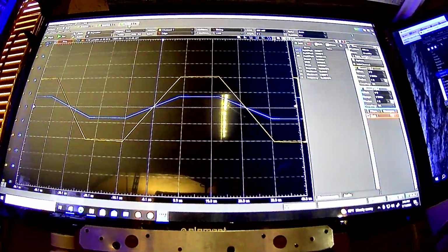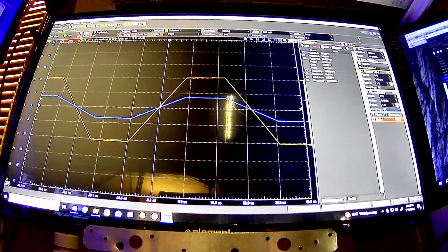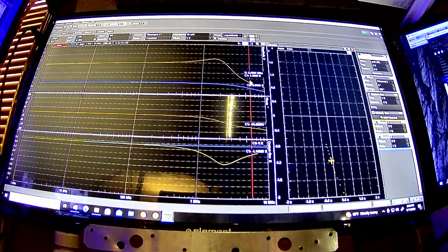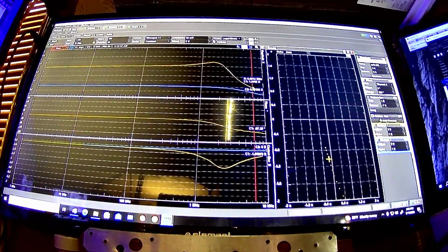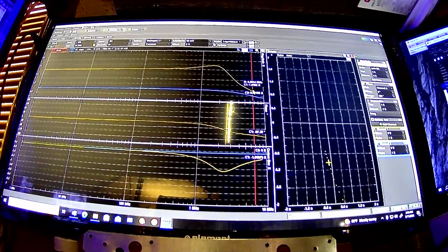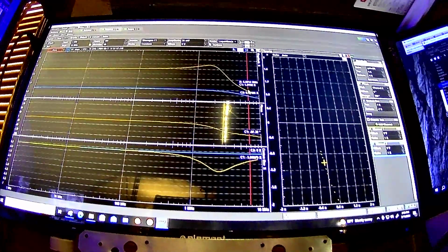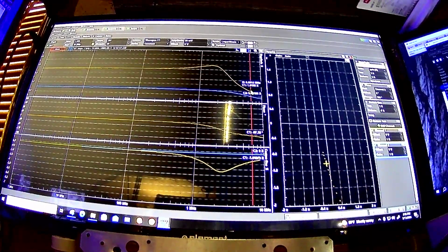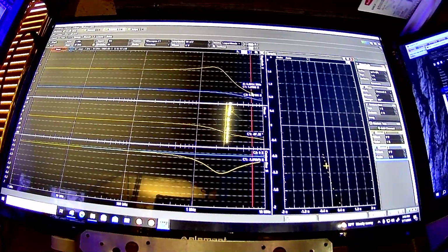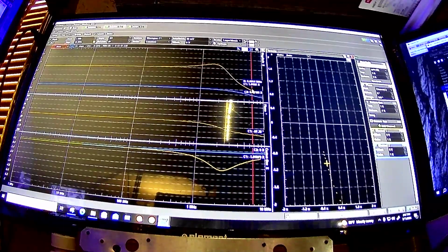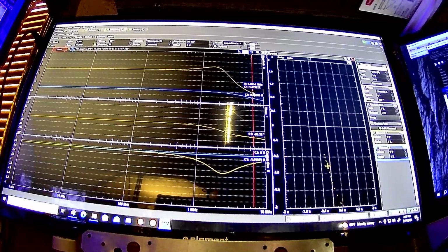Now, because this NE5532 is a 10 megahertz op amp, and it's showing unity gain down to about 6 megahertz here, which we got set to a gain of 3, that may not be unreasonable. I'm not sure, because we're running out of loop gain basically. We totally ran out of loop gain well before this, in fact. I don't know. I'd have to configure it as unity gain to see if this would be any different.